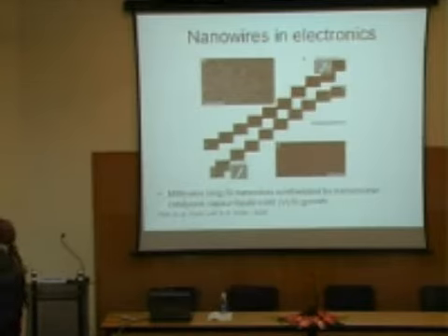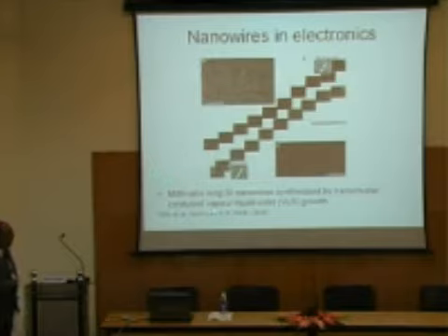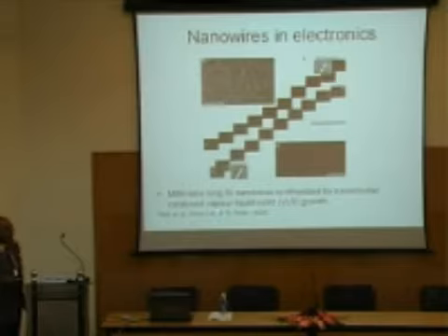This is silicon nanowires, and it has been grown by a very standard technique of growth of long crystals. So earlier people used to make large crystals of silicon to make single crystalline silicon wafers, and nowadays people are using the same technique to make thin wires.